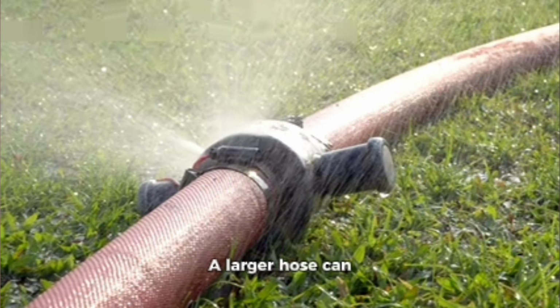Let's start by calculating the total load for the office. In this case, the total load is 57 kilowatts. From this, we can calculate the current needed to select the right protective devices, like the incoming isolator and the ELCB. We use the formula: current equals the total load, divided by the square root of 3 multiplied by voltage and the power factor. For a three-phase system with 400 volts and a power factor of 0.8, the current comes out to approximately 82.3 amps.